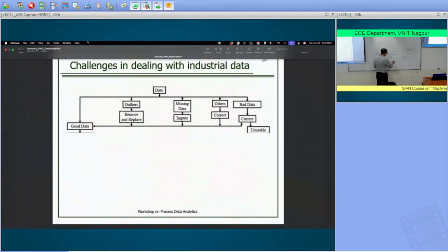So let's take another example where they are not an outlier. So I'm going to take the same system, but I'll do something slightly different. Okay, so let's say I notice this. Now I don't want to immediately conclude that these are outliers, because if I had also noticed a change in the valve position, okay, I open the valve up and I see the level going up, and then I closed it and the level comes back down, right? So then that's not an outlier. That's a true representation of the process. So outliers are measurements that don't reflect the true behavior of a process.